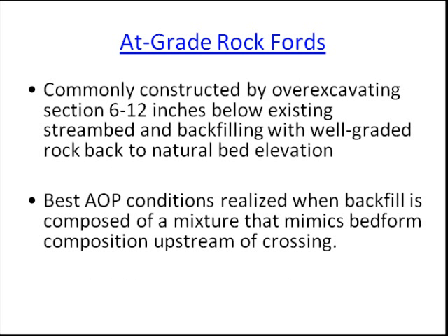When rock is added to a crossing to improve the travel surface, there's a danger of building a sediment surface that creates passage problems because of turbulence or depth and velocity problems. In addition, if rock backfill isn't well graded, water can flow through instead of on top of the travel surface.